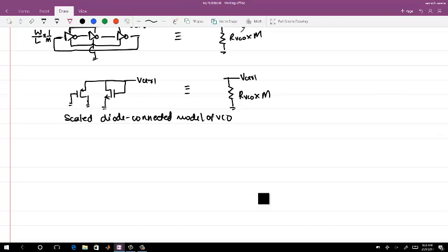Why not spend the same power in the... No, your replica is scaled. How much? So the thing is, you always make a comparison. If you find that spending 20% more in an actual regulator gives you a better PSRR, you would go and do that. But normally it turns out that is not the case.